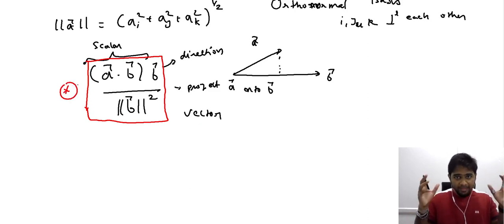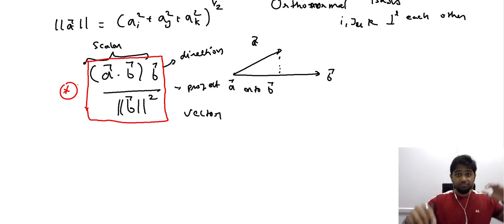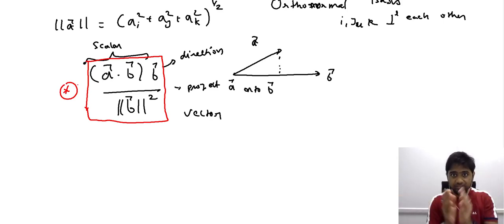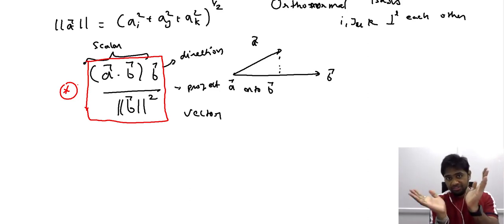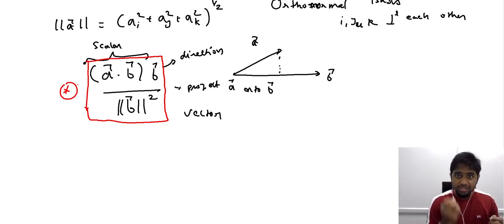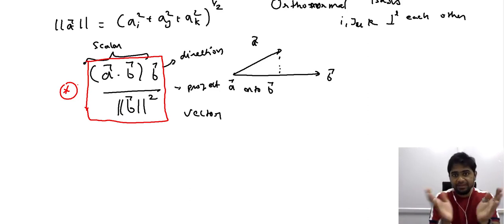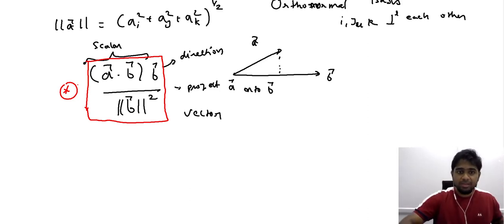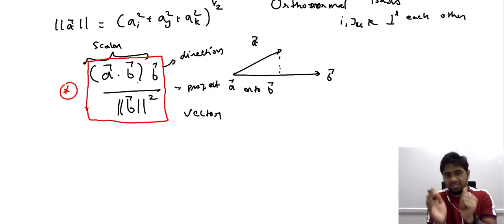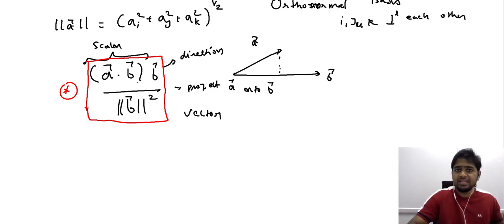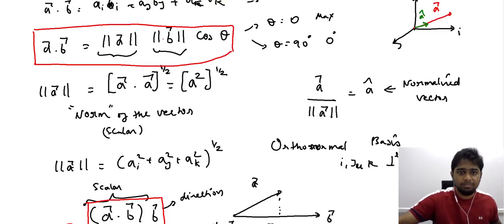Now the approximation, when we use the dot product for dissociating the load into the different directions, that is the normal and the shear direction, we made some assumptions. We already fixed our directions, and we also assumed that these directions, that is the B vector, are unit vectors. So once we assumed that the vectors along the normal and along the shear are unit vectors, it allowed us to substitute B as 1, and all that we are interested in was A cos theta.